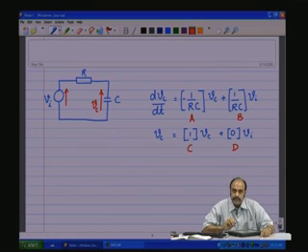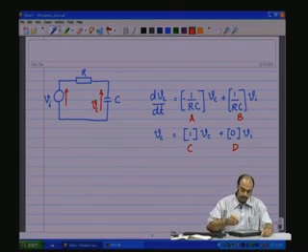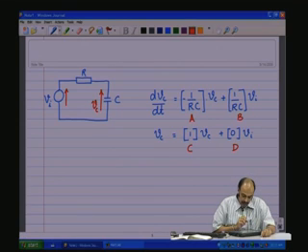These are the four matrices that you have to always feed in, whatever may be the system, because all the systems are described in the standard state space form, which is x dot equals Ax plus Bu, y equals Cx plus Du. And normally to study the system in the time domain, the step response is a key response that gives almost all the characteristics of the system in the time domain.